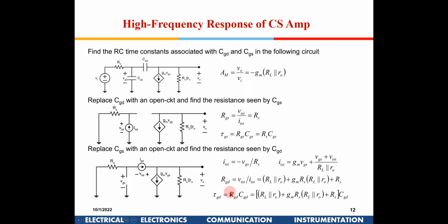Yes. Okay. Now when we see this, this is the equation which I get. This is a big equation. Now if I neglect this, this is just the second pole. One pole is here already; this is about the second pole. So this resistance which we got, I am multiplying it with the capacitance under consideration. So this is RGD into CGD, because we applied this test at the particular position where the capacitance CGD was there. So I am multiplying it with CGD to get that pole with this expression.